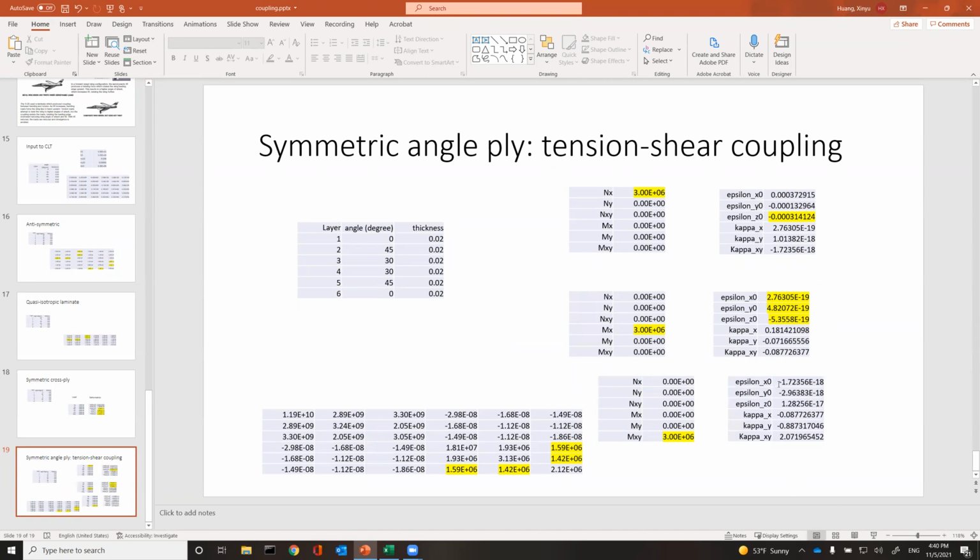Oh, you see here, these remain 0. These are the extension deformations. And you have a twist for sure. When you apply twist, you have twist. The twist is pretty big. This 2.07 is the twist, right? But you also have bending. So when you twist it, this material also develops a curvature in the XY direction.